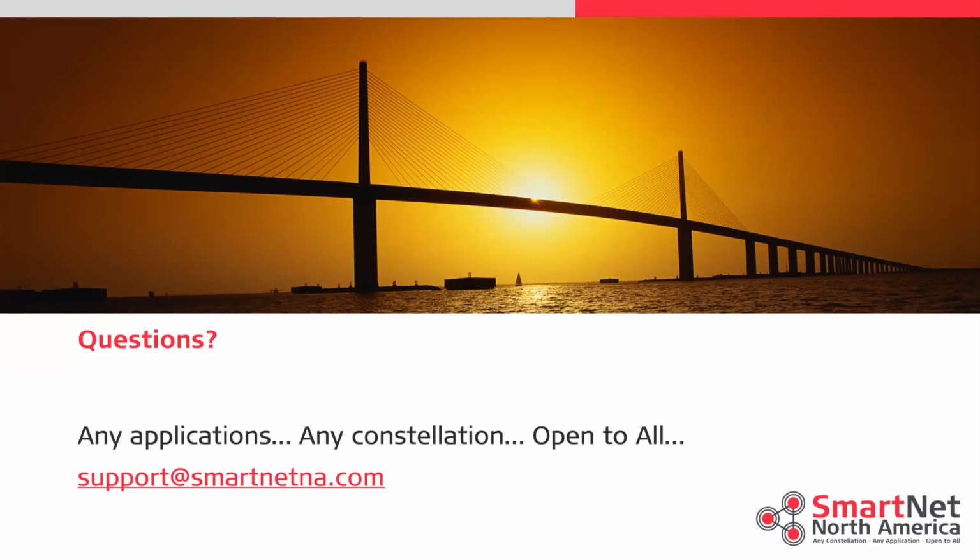How you tie into passive control ground monumentation is really, unfortunately, irrelevant. I know that it seems like it's very relevant to most folks, but that passive monumentation necessarily hasn't been reobserved in the same time period that the active reference stations have been collecting data. How they may or may not fit depends on where you are. In Louisiana, you've got subsidence. In California, you've got movement. And up north, you've got glacial rebound. So there's always movement happening to the ground where a passive monument could be.